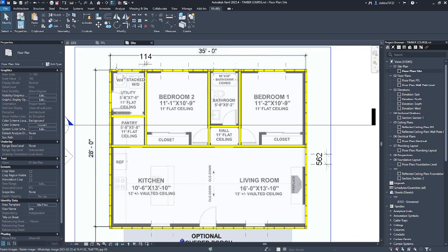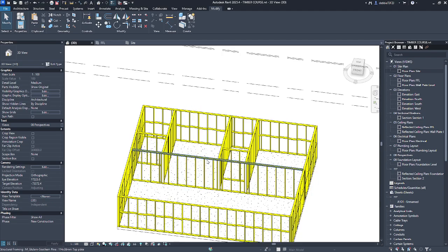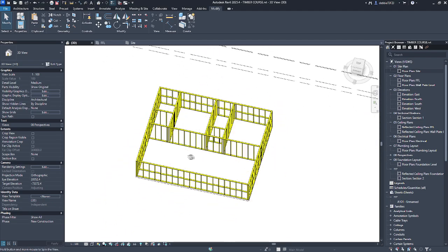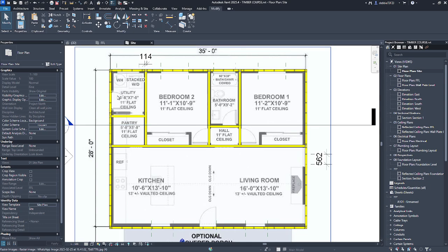So for the next lecture, we would be doing all our openings for our windows, doors. We'll be doing that. And then once we have completed our window and door openings, we will start with the interior side of our walls with a 16.5mm plasterboard, which we will be adding individually to each wall to make sure everything runs smoothly with a corner sweep on the interior side.